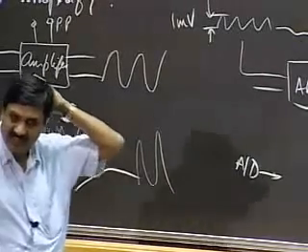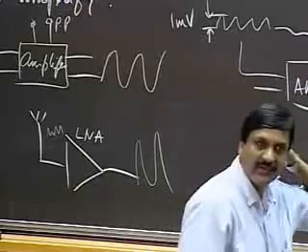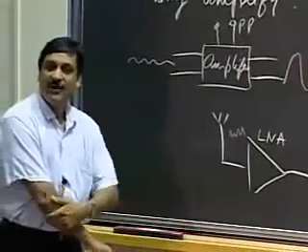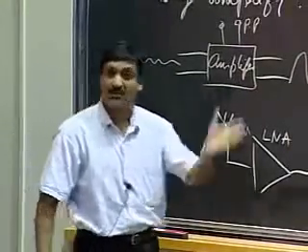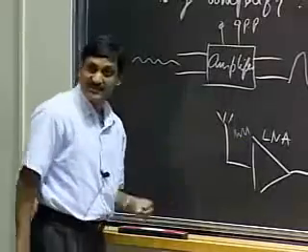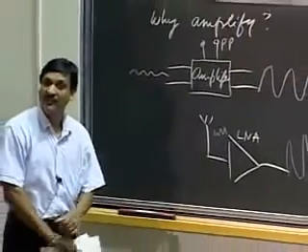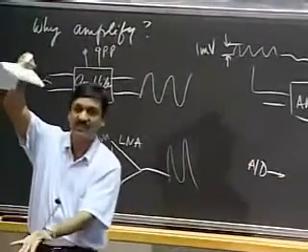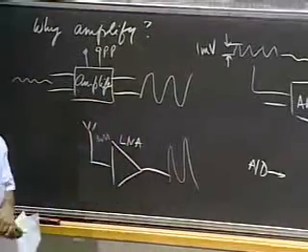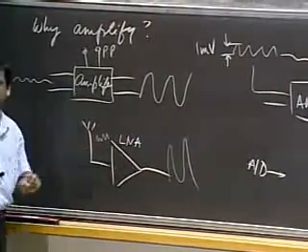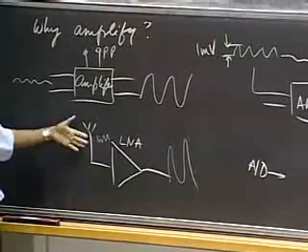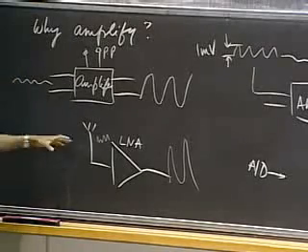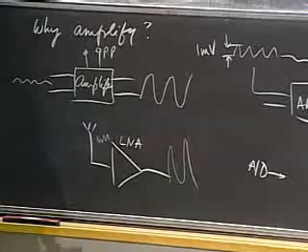I recall last week, I asked somebody in class how we would transmit the signal from point A to point B without being impacted way too much by noise. And he said, oh, go digital. Good point. If I go digital, I can transmit the signal without noise being a real factor. But then the analog to digital converters need the signal strength to be a given value before they can chop it up into digital levels. So an amplifier is very fundamental. In this case, what may be a signal of a few tens of microvolts has to be amplified to some large enough value that it can be further processed.